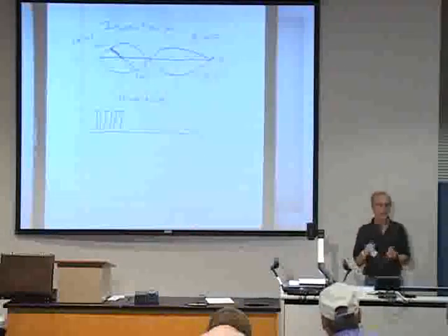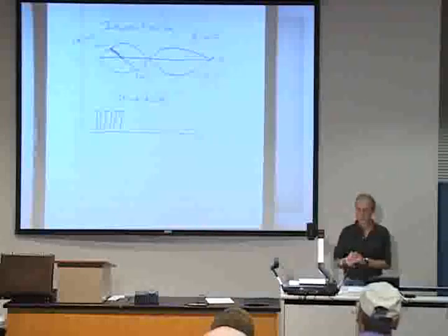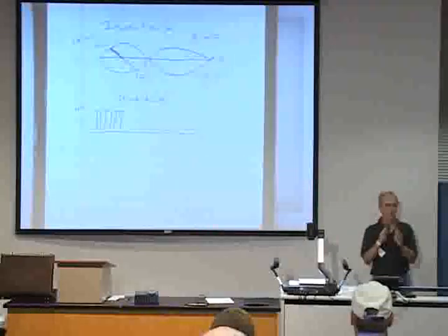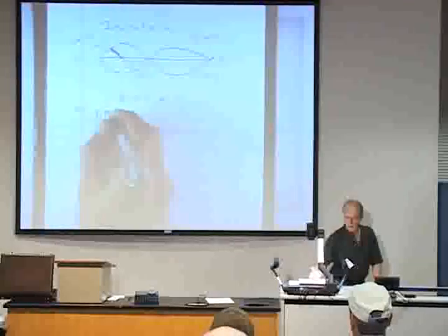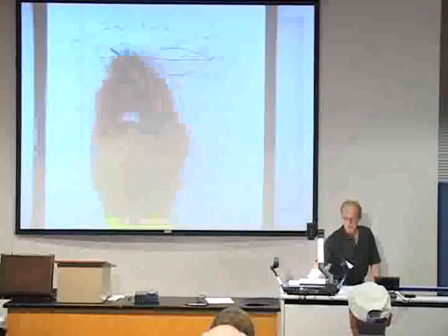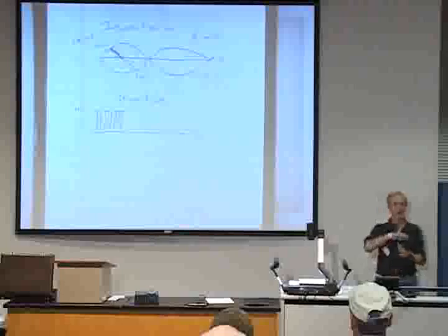And so what they do is they turn it on at maybe, it might not even be 160, it might actually be 120, something like that. They will turn it on for a fraction of a second, turn it off, turn it on for a little longer fraction of a second, turn it off. And so they do that in pulses. And so the total area underneath these pulses while it's turned on will be approximately the same amount of area underneath a true sine wave. And so you can fool most equipment into working properly with a modified sine wave inverter.